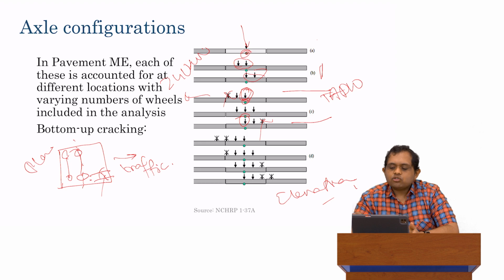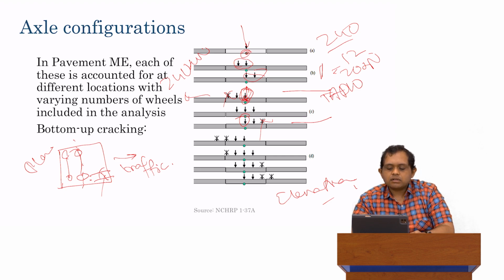So the load on each wheel is going to be 240 divided by 12, that's 20 kilonewtons, right? And so what we will consider is, in these two cases, we put an 80 kilonewton axle above this point, and next to it, we put another 80 kilonewton axle.